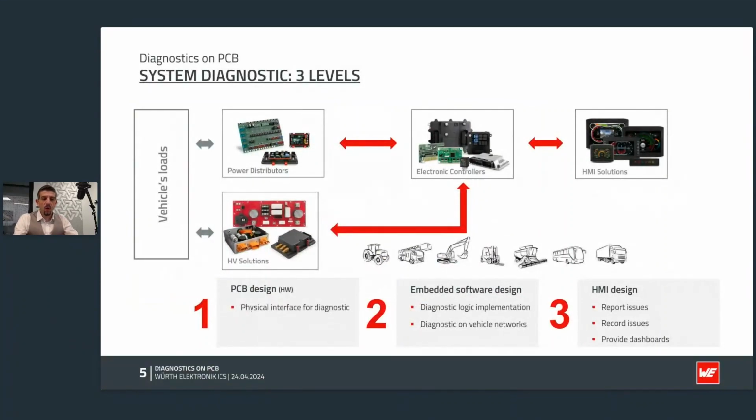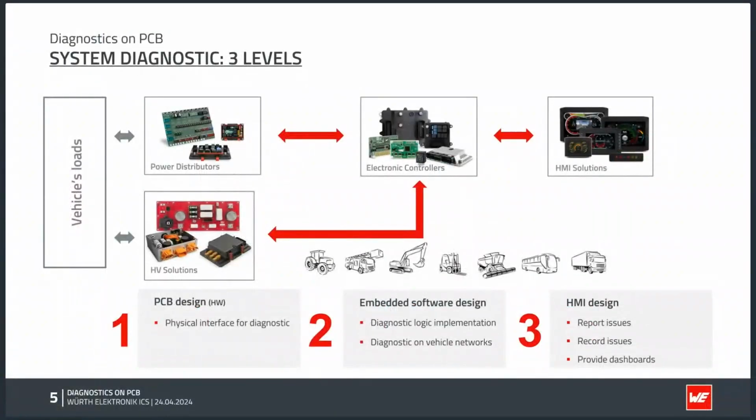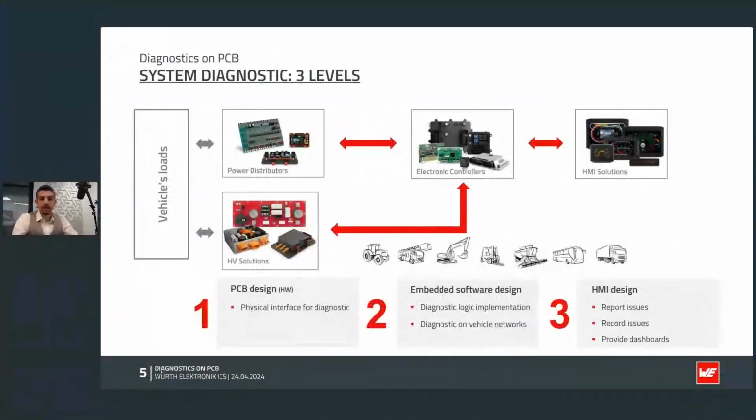Indeed, it is all about the function of each part of the vehicle, each load which is driven. And this is where the questions are. Is the load powered? Is my system ready to power my load? How is the health of my system? Is my fuse blown? Is my load okay? So many questions and much more actually. We won't speak too much about preventive maintenance or any highly communicative aspect today. But the fact of being able to get a diagnostic, a status of the electrical system, of the load attached or driven from an electrical central unit is the starting point of a wide array of possibilities.